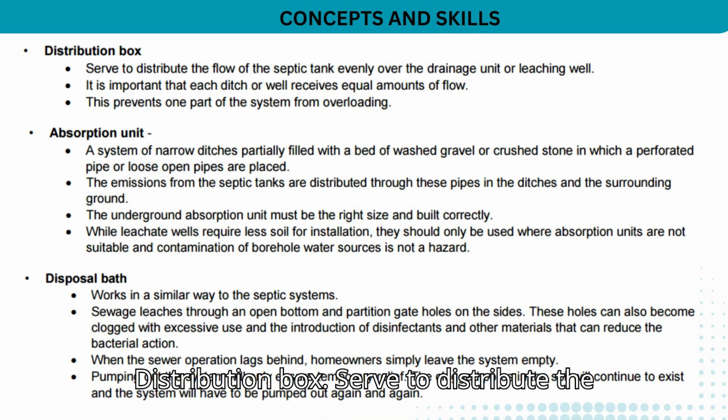Distribution box. It serves to distribute the flow of the septic tank evenly over the drainage unit or leaching well. It is important that each ditch or well receives equal amounts of flow. This prevents one part of the system from overloading.